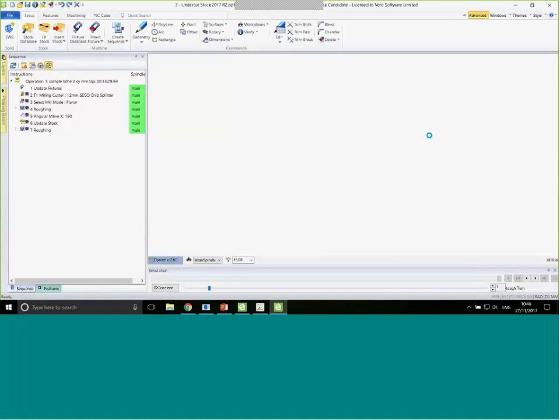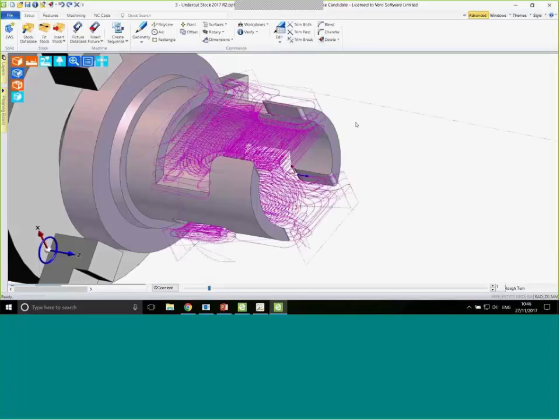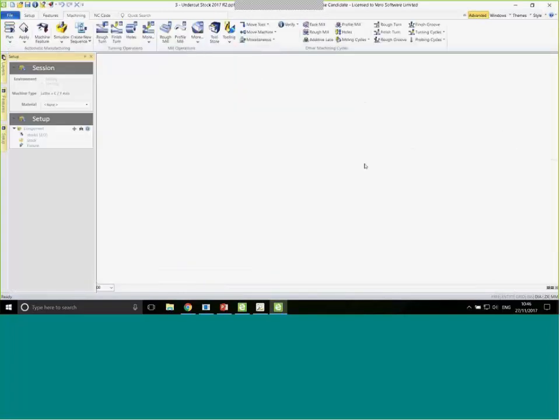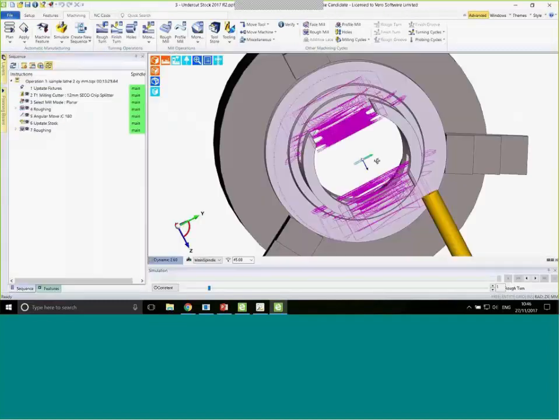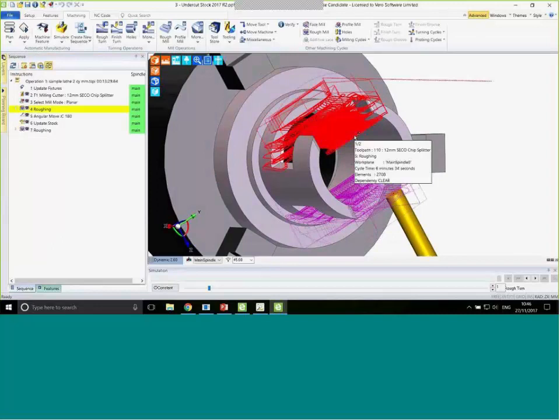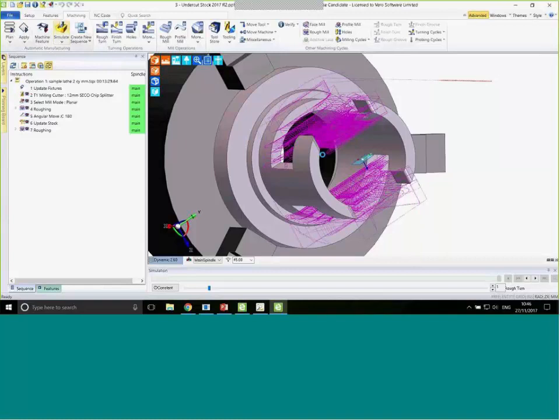And the other one is, and this again is a very interesting one. Where is the room for improvement with the roughing cycle with respect to the stock? And so we see here that this is a tube of stock, but we've got toolpath where really there shouldn't be toolpath. So this is 6 minutes and 34 seconds of time. And we'll just throw this into the machine simulator.